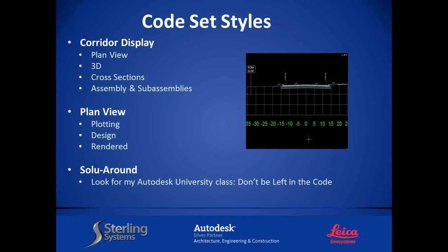I can look at my sidewalks, but even more powerful than what it's doing here, I can see offset information. I can see every single pavement slope. So if I'm going through a super elevation, it's going to tell me exactly what it's doing right then and there. I have between my sidewalk slopes display, my cut and fill slopes, like 4-on-1 or 3-on-1, automatically display. It tells me where the right-of-way is. There's so much information that we didn't use in the past because it wasn't available to you.